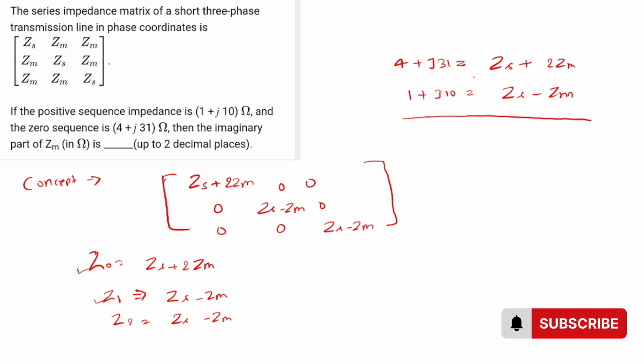If you subtract the second equation from the first, 4 minus 1 is 3, and 31 minus 10 is j21. Zs cancels out, and 2Zm plus Zm is 3Zm.